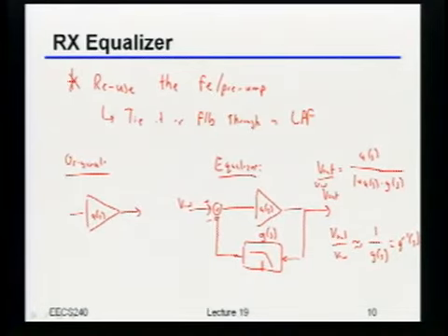Ideally speaking, again, in our context of the high-speed link here, what would you want to put into this feedback loop right here? The channel? Yeah, I want to put the channel. Okay, so now why is that slightly problematic? Area? Well, yeah, it is actually area, but it's not even just your chip area. It's the entire board, right? Because you'd have to take the entire trace and everything and somehow take it out and come back. I don't exactly know how you do that. But you're exactly right. You want to put the channel.